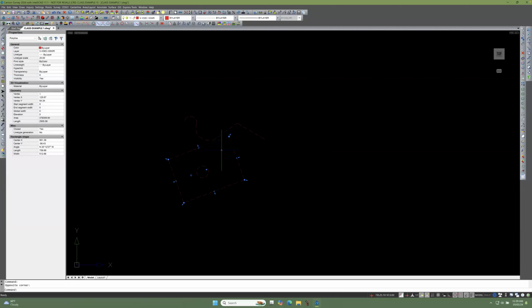You can also select a circle and change its properties. You can change its center X, center Y. So if I choose that center X and type in a number, or if I click that little icon right there, it lets me pick a point. So I'm going to put it down over here in the X direction, but notice when I go over here, see it's changed that location. Do the same thing with the Y, and it follows X and Y. It brings the whole thing around.